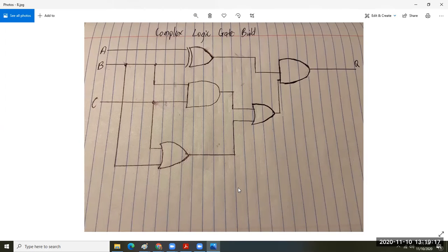Does anyone have any questions about this logic gate before we continue? No question. Okay. I like the fact that the ANDs and the ORs are arranged kind of in parallel. So in other designs, you see the ORs over here and the ANDs out here, or the ANDs over here and then the ORs out there. But you see an early AND and an early OR, and then you see a later AND and a later OR. So that's going to make life interesting for the behavior of this thing. Yeah, I like that.